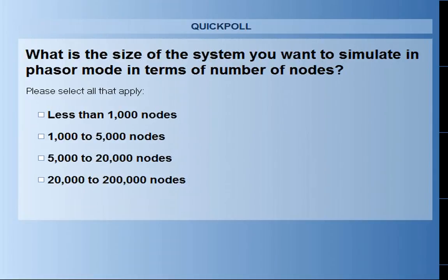If you go into the PMU location, you can see the voltages and the angle difference. In the others, you can have several different types of views. For example, here I have the frequency of the system, and in this one I have the power which is transferred between transmission lines. But the favorite one of everybody is normally this view, where you see exactly the RMS value and angle. Actually, you are seeing the phasor data here very live.